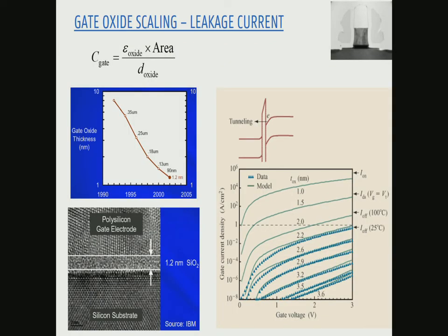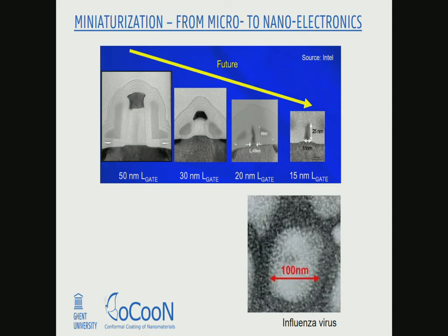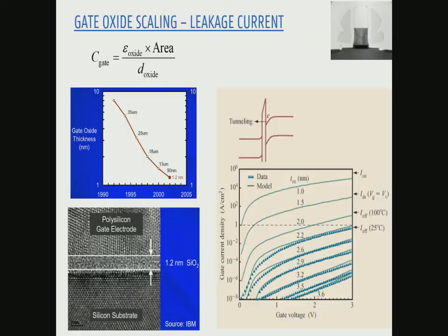And the way microelectronics works is that every year or every 2 years you want to scale, so a transistor that is now this size, you want to scale it to half the size and half the size and so on. So you have this scaling law where every couple of months or years you want to decrease the overall size of your transistor. And the point is, at some point, if you decrease the width of your transistor, for it to still function, for a long time you also had to decrease the thickness of this critical gate oxide layer.